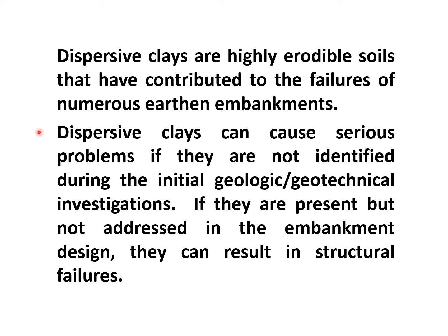Dispersive clays can cause serious problems if they are not identified during the initial geologic or geotechnical investigations. If they are present but not addressed in the embankment design, they can result in structural failures.